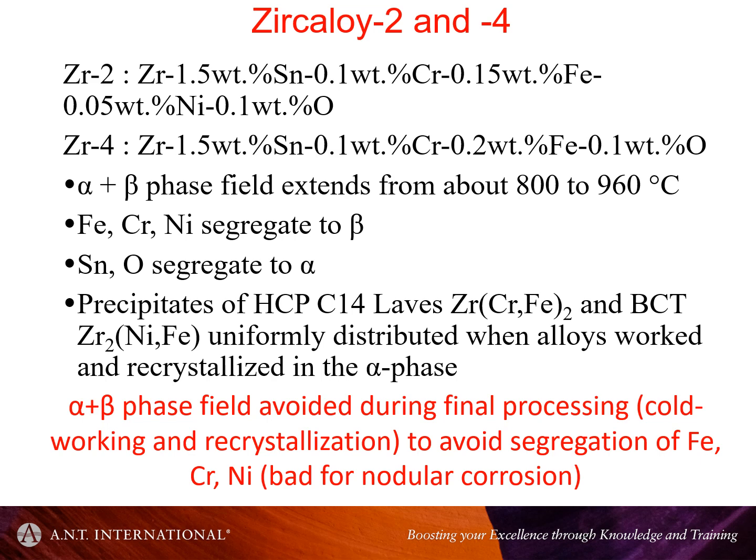So this is the composition of zircaloy 2 and zircaloy 4. The main precipitates are C14 Laves phase and body-centered tetragonal Zr2NiFe.